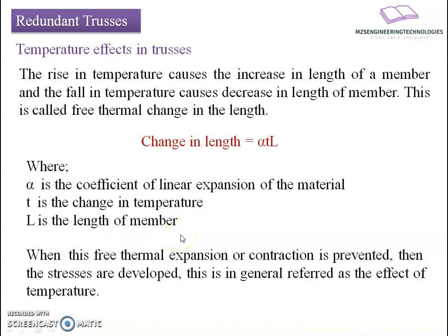When this free expansion or contraction is prevented, then stresses are developed. This is generally referred to as the effect of temperature. In the case of a statically determinate structure, the free thermal expansion and contraction is not prevented, as the members are free to adjust themselves or deform to compensate for the change in geometry.